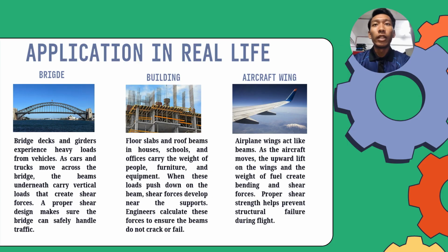And then we have buildings. Floor slabs and roof beams in houses, schools and offices carry the weight of people, furniture and equipment. When this load pushes down on the beam, shear force develops near the supports, so engineers calculate this force to ensure the beam does not crack or fail.